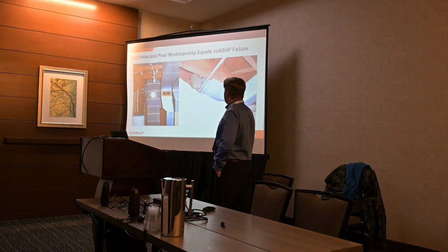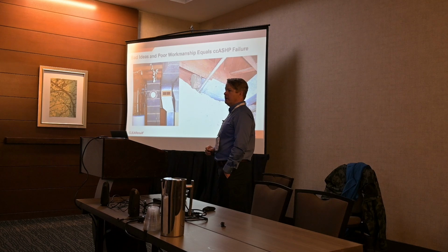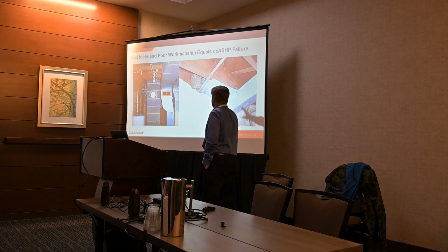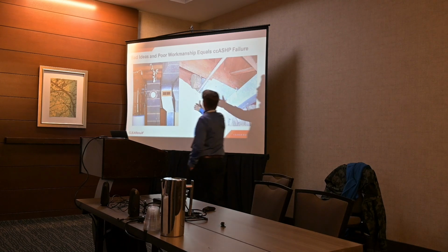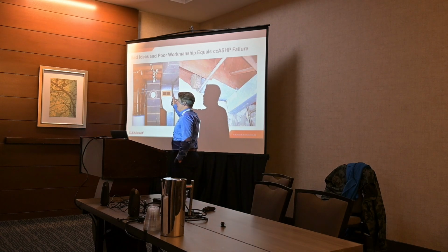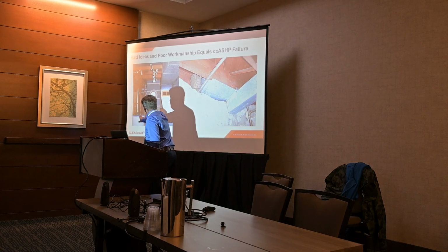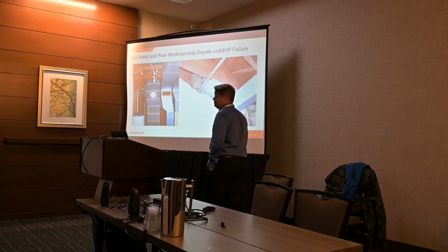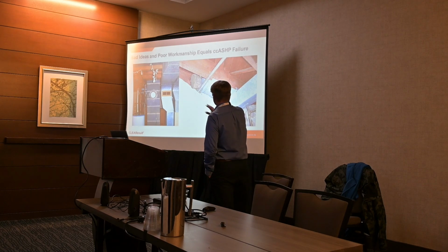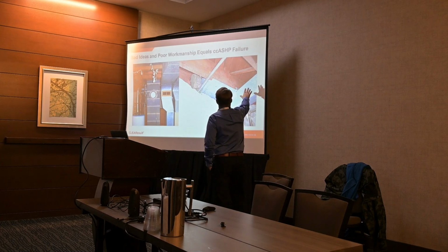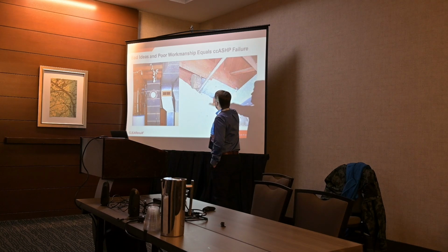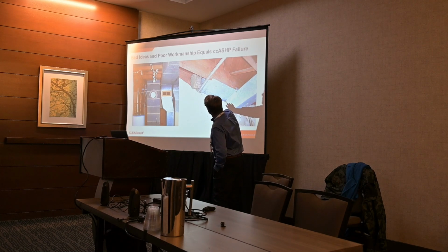Where is return air supposed to come from? The house, the living space. It comes from conditioned space, it goes through the unit, and it goes back to conditioned space. This is nothing but a gigantic return side leak in a space that has 2 category 1 natural draft appliances. What could go wrong, right? This is the kind of stuff we have to stop. We've got to seal these up really tight, and we can't have this kind of panning and this type of leaks, right?